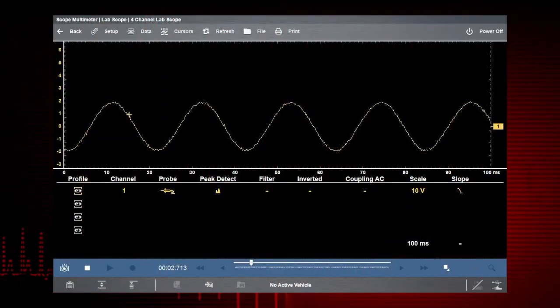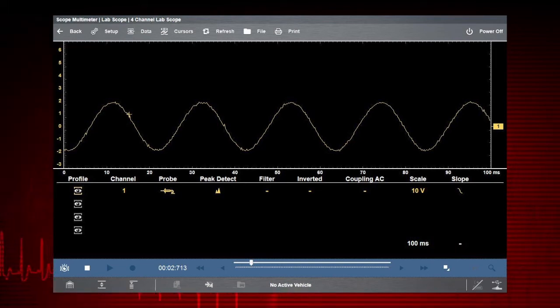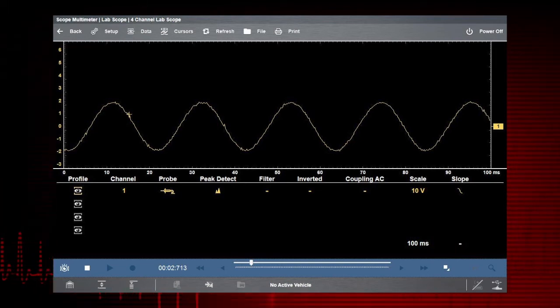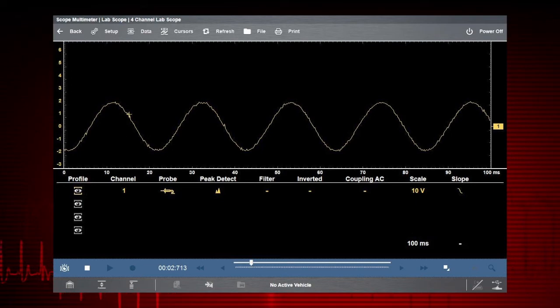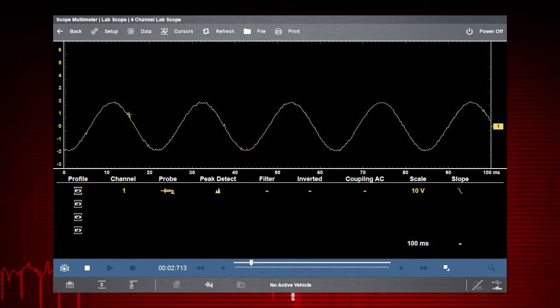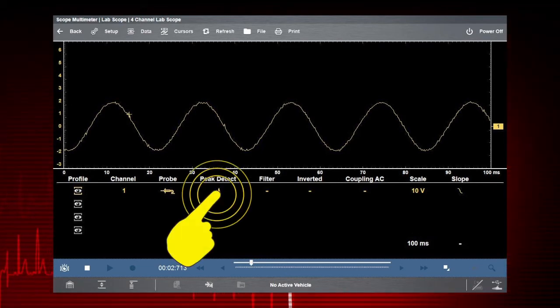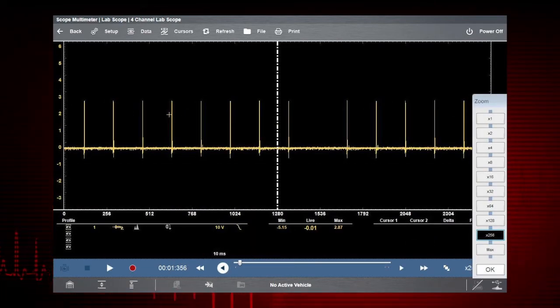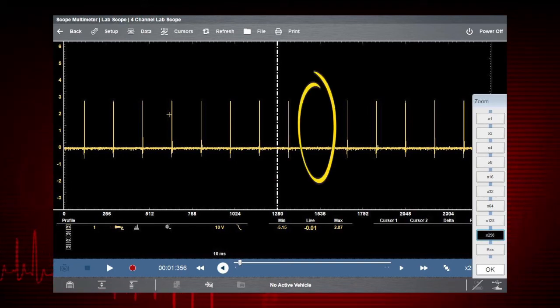At 6 million data samples per second, the Snap-on Scope function can capture many more samples than displayed on most standard display screens. To sample at the maximum rate, select the Peak Detect function to capture extremely fast peaks and glitches, like this missing ignition spike.